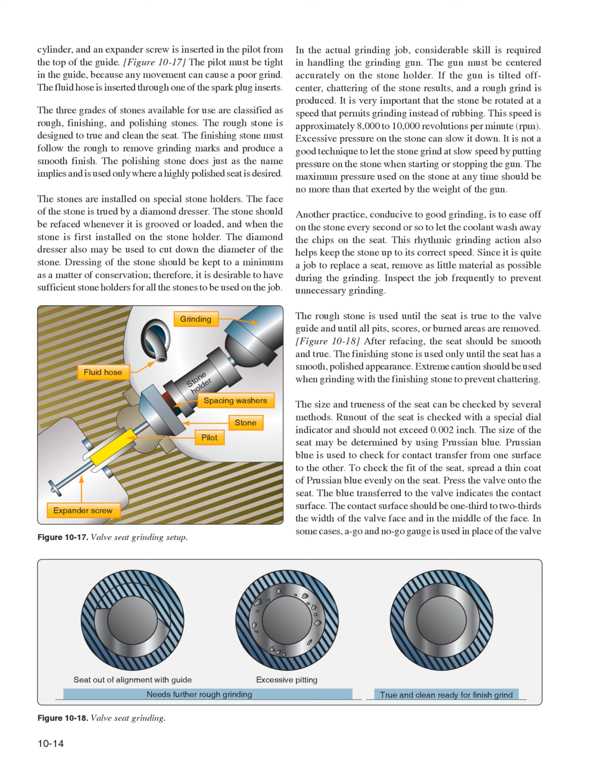The stones are installed on special stone holders. The face of the stone is trued by a diamond dresser. The stone should be refaced whenever it is grooved or loaded, and when the stone is first installed on the stone holder. The diamond dresser also may be used to cut down the diameter of the stone. Dressing of the stone should be kept to a minimum as a matter of conservation, therefore, it is desirable to have sufficient stone holders for all the stones to be used on the job.